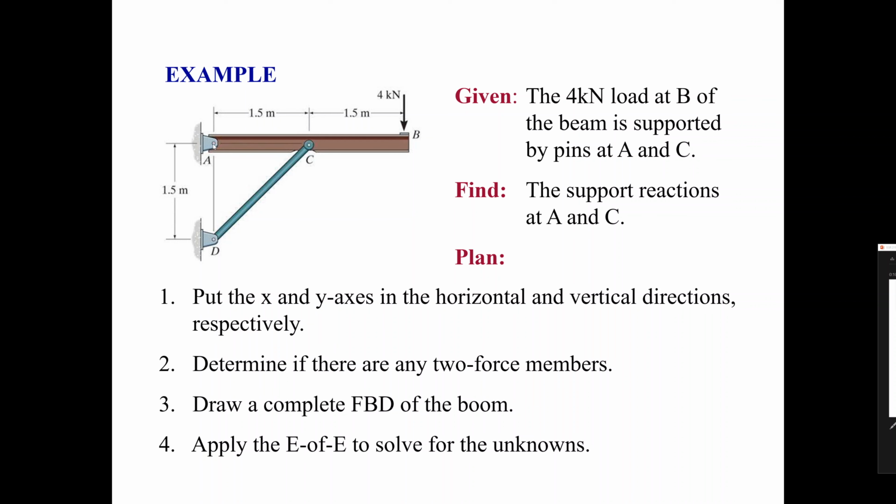And we also have reactions at point A. Well, this is a pin support, so it doesn't have a reactive moment. So we're going to have a reaction in the x direction and a reaction in the y direction. Right off the bat, you have an unknown force here, an unknown reaction in the x direction, and an unknown reaction in the y direction. So we have three unknowns, and with three unknowns, we have three equations: forces in the x direction equal to 0, forces in the y direction equal to 0, and moments about any point equal to 0. If we use those three equations, we can solve it.